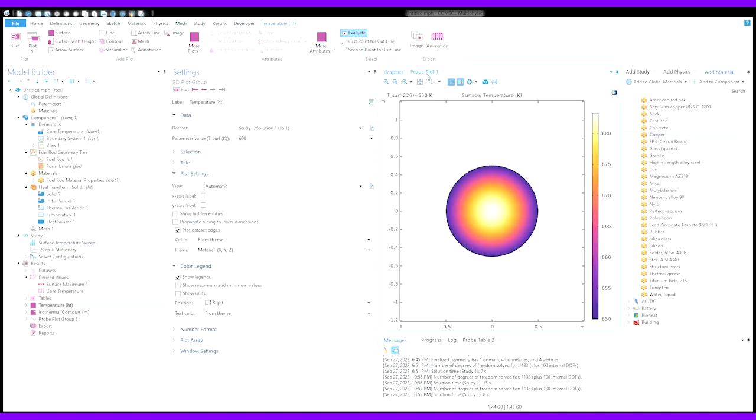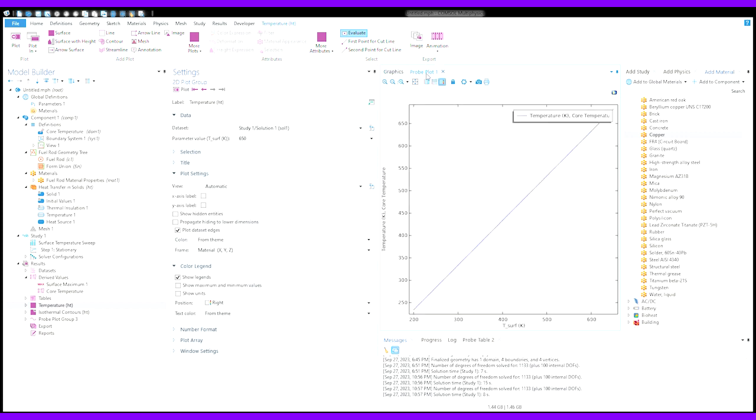So this is a very simple simulation, so it doesn't take too long. But I would recommend, if it takes your simulation longer to run, I would start with bigger steps and do a bisection method to make your sweep range smaller before you increase your step size.